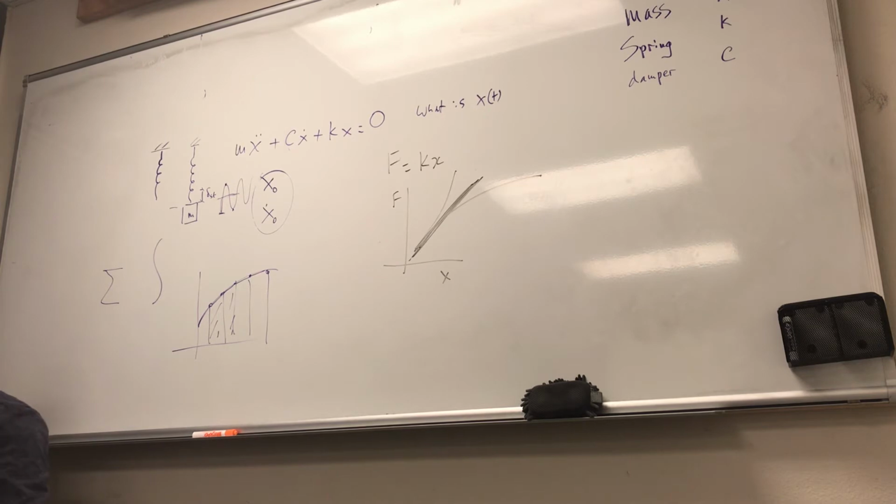So in some cases, the excitation is non-deterministic or random, and the value of the excitation at any given time cannot be predicted. An example of random excitations is wind velocity. Sometimes you have gusts, you have this and that. Road roughness, how do you know? Nobody has mapped how that road roughness is going. And ground motion during earthquakes.